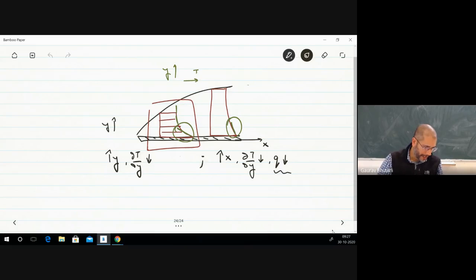So what we say is that as my x increases, my h, what do you think? Is my h increasing or decreasing with increasing x? Decrease. Decrease. Okay. So the heat transfer coefficient decreases as you go further in this solid and along the length of the solid. Okay, this is a flat plate. That's an idealization, but the idea is similar for curved bodies as well.